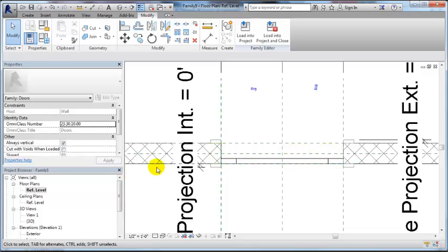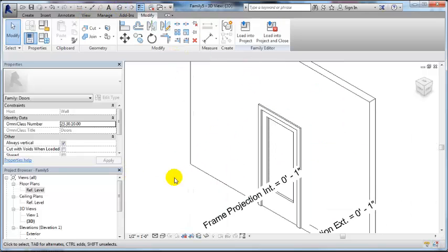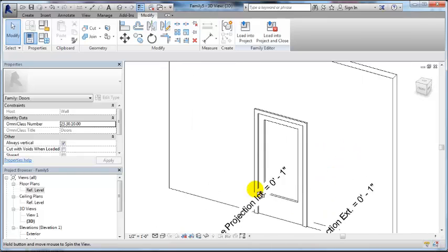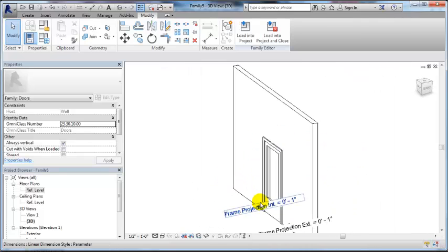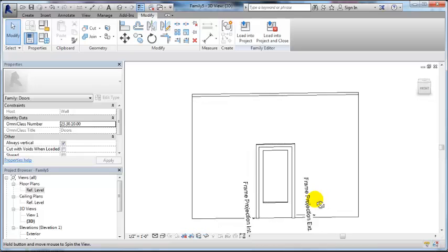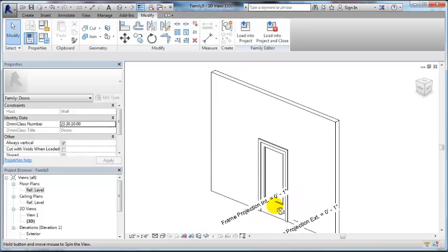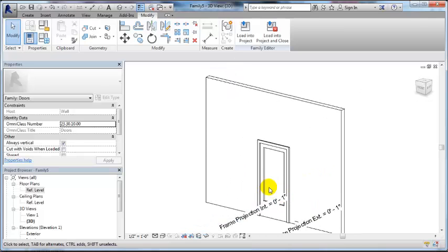So now I can continue forward. So let's go back to the 3D view, and we have our door, and we're going to put some glazing in there, and we're going to add the swing and so on. So let's go ahead and add the swing next. Now, not all the doors work the same in Revit, but the door that I'm going to do for this scenario, the swing is going to be represented with symbolic lines.